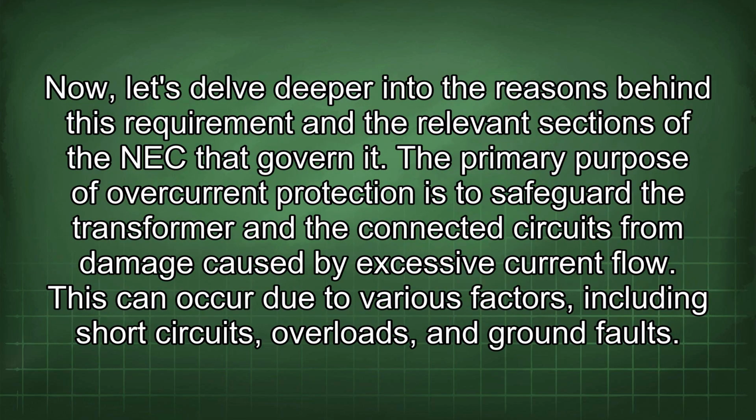Now let's delve deeper into the reasons behind this requirement and the relevant sections of the NEC that govern it. The primary purpose of overcurrent protection is to safeguard the transformer and the connected circuits from damage caused by excessive current flow. This can occur due to various factors, including short circuits, overloads, and ground faults.